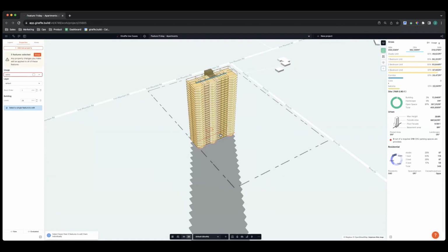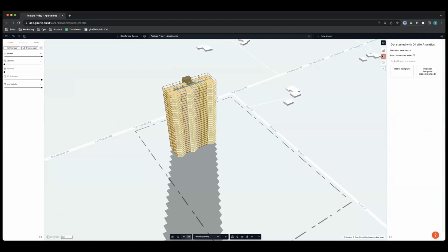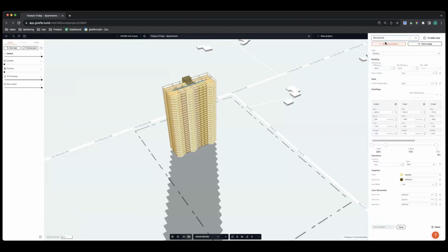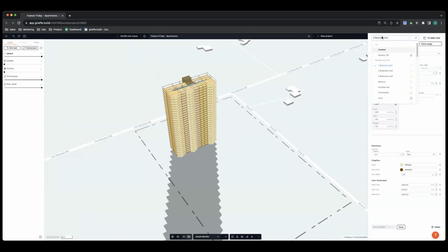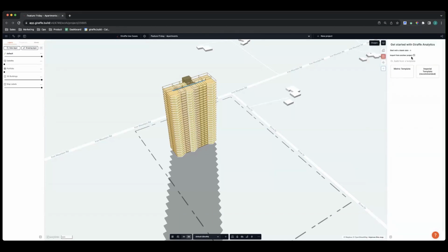So what we're going to do now is move into analytics. Analytics is a piece of Giraffe that allows us to customize the way things are calculated. You'll remember a few things about what we've shown so far. One bedroom units have 100% efficiency for both FAR calculations and net rentable calculations. Corridors core have 0, 0 for core. Corridor has 100, 0, because most FAR makes you consider corridor as well, although it might be 0 for you. And then our balcony is again 100, 0, because balconies can often contribute to FAR. So let's go build that out.